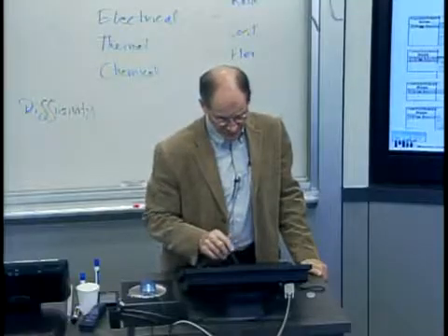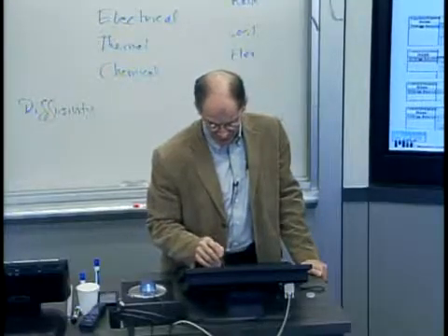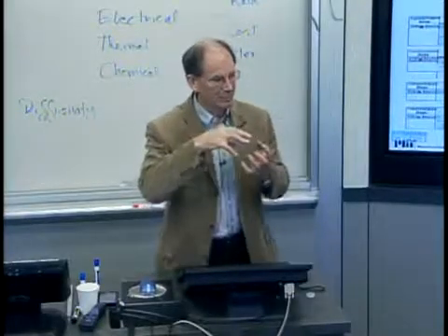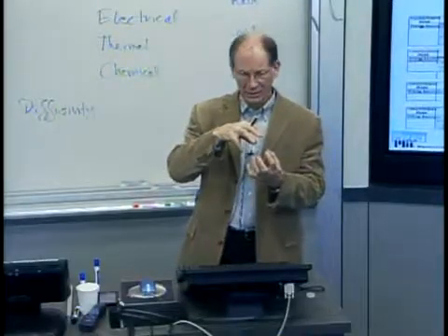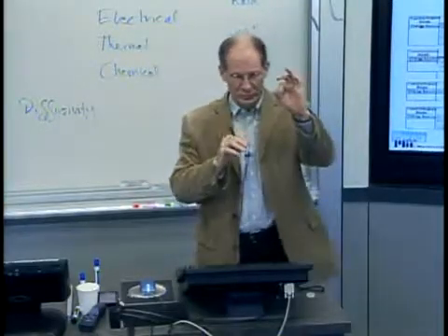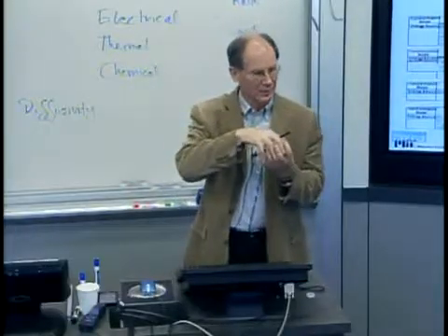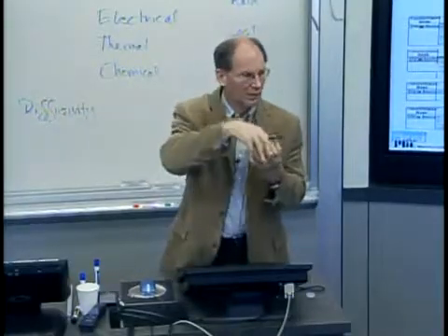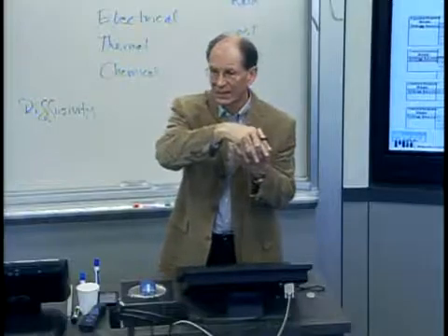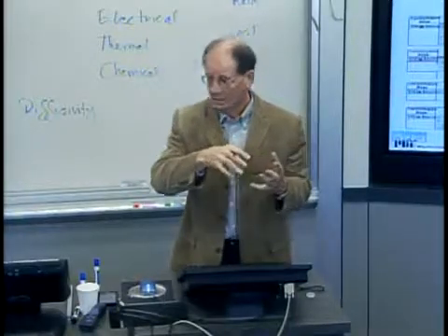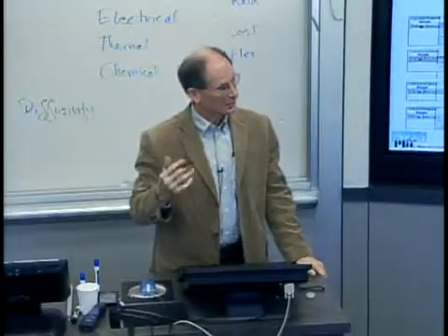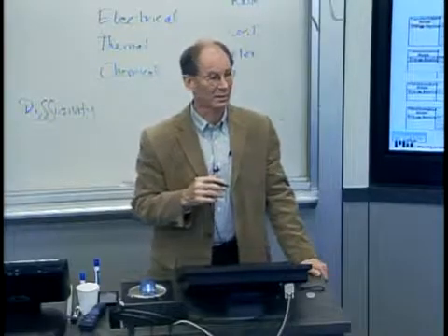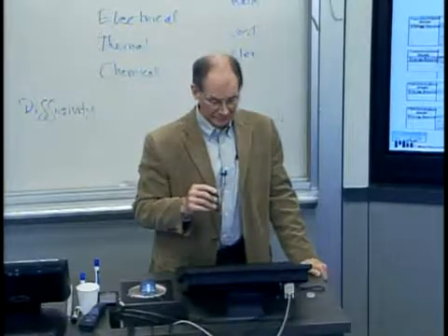There's a bunch of other ones here. One of the interesting things is if you come over here to something like hot isostatic pressing, a powder metallurgy or powder ceramic process where you take uniform powders and compress them in a mold. So that's obviously an addition process, and then I sinter them, and then I do other stuff to it, and I do it all at once in a form tool, a can, and I'm all set. That's clearly a parallel process, and the result depends primarily on the shape of the can.